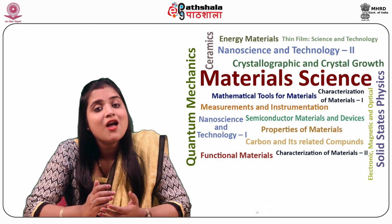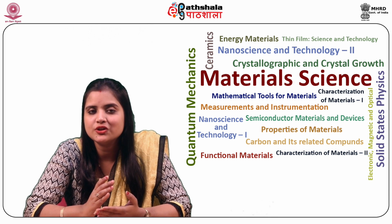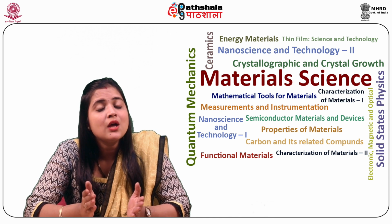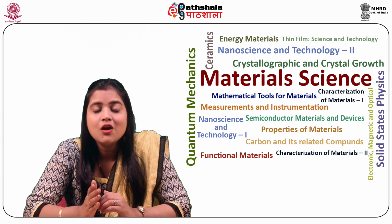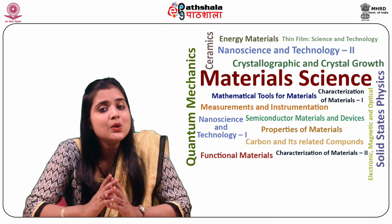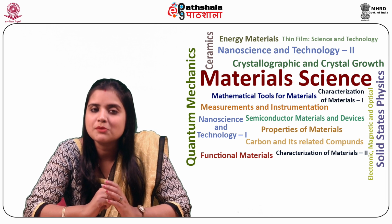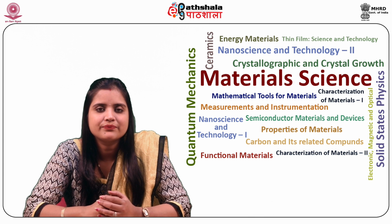Such properties of thin films are highly structure dependent. The conductivity of thin films varies with the orientation of the normal to the surface with respect to the crystallographic axis, even for materials having cubic symmetry, such as silicon, for example.